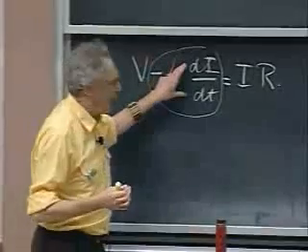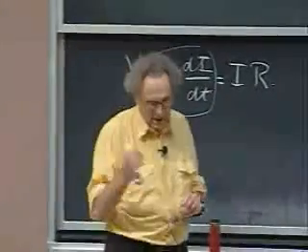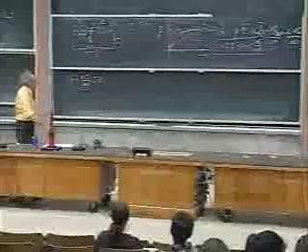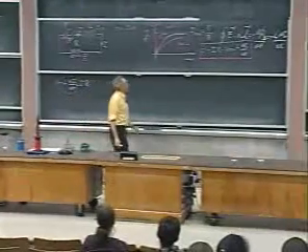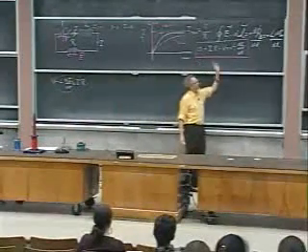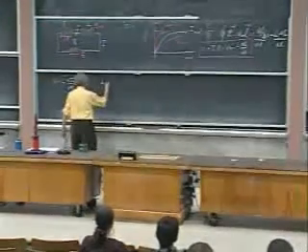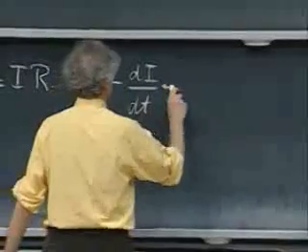It's not until di/dt has become 0 that V equals IR. And that happens, of course, if you wait long enough. And so we have to solve that differential equation. What is often done is that you bring all the terms to the left side and you get a 0 on the right side. And so what you often see is that L di/dt plus IR